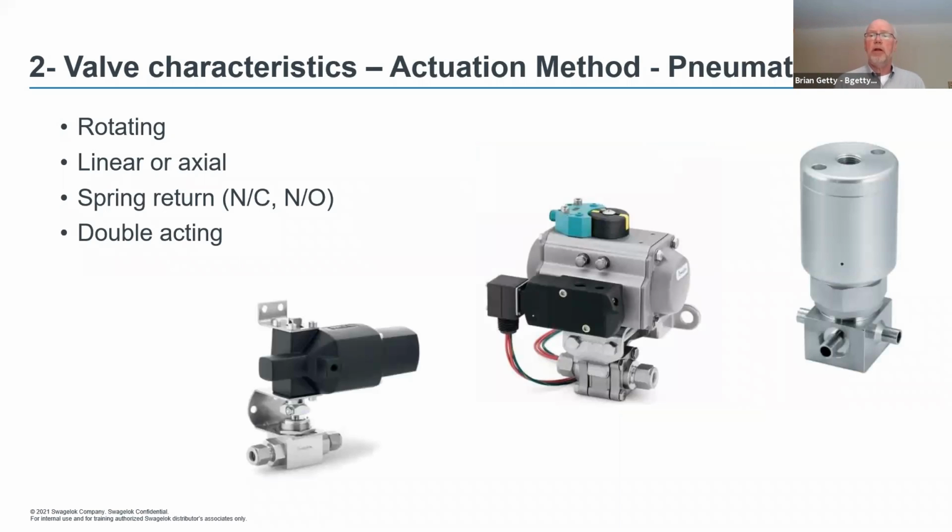Is this valve going to be installed 30 feet in the air? If it's 30 feet in the air, as an example, you're not going to be going up there on a ladder to activate a valve. So at that point, you can go to a pneumatic actuator, pneumatically actuated valves. Here you've got a spring return valve.